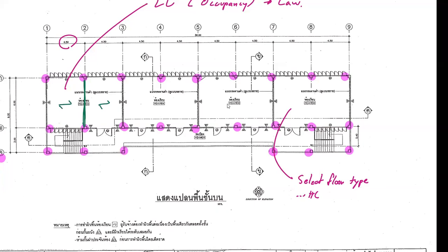4.5 meters is pretty doable. Okay, so for those of you who want to go ahead and try to study how you can select the hollow core, you can do so. I can provide the tables for the hollow core that you can pick from. And the thing is this, now when you select the hollow core from the catalog, you know the span length now, right? It's going to be 4.5 meters.